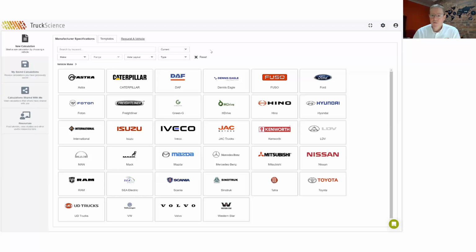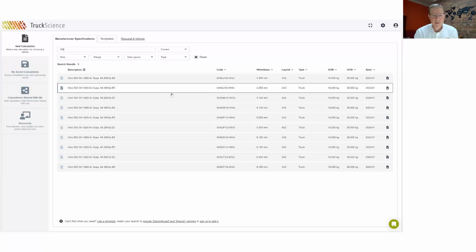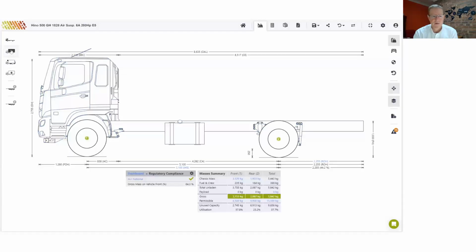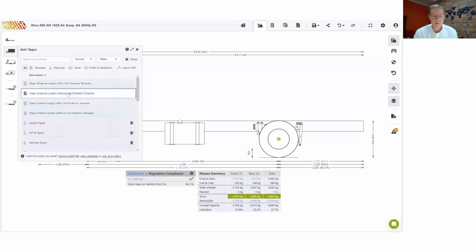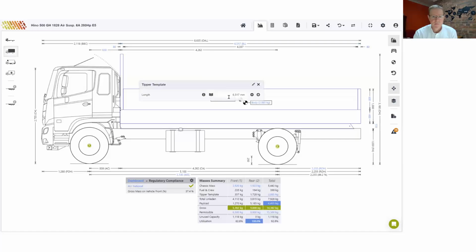Could you please show an example of a truck build where we have a combination tipper and storage boxes that sit across full width of chassis? Maybe that's a nice one, Tony. We still have a few minutes. You can just open any chassis and put on maybe a template dump body and use the other equipment to show some toolboxes or any other equipment and show that across the width of the chassis. You can probably do that in the top view.